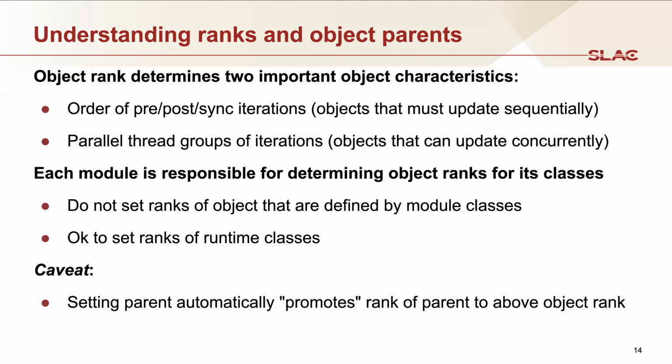I don't recall whether nodes or links are higher or lower rank, but in any case, you only have two ranks for Newton-Raphson, one for nodes and one for links. So you can see that according to the solver method, the ranking system would be completely different. In fact, the Newton-Raphson solver gives you a very flat rank hierarchy, only two high, and a forward back sweep gives you a very deep one.